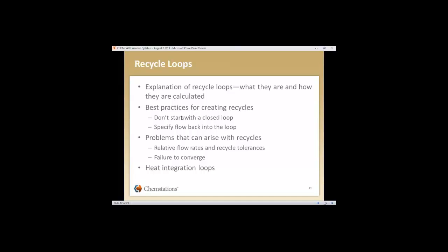The most important thing, don't start with a closed loop. If you make mistakes entering numbers into CHEMCAD, if there are mistakes with the numbers that were given to you, if the situation is just more complicated than anyone realizes, a closed loop could give you problems failing to converge. With an open loop, it's very easy to see those problems and then make adjustments or explore theories.